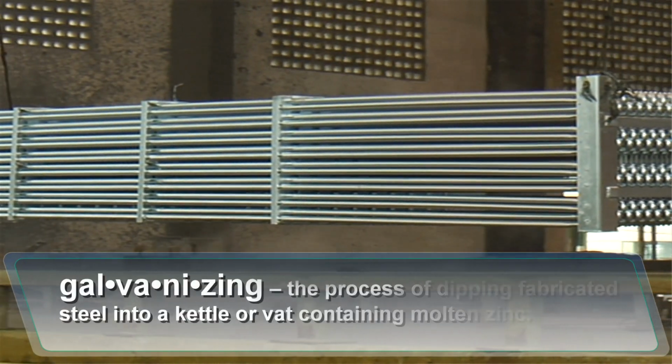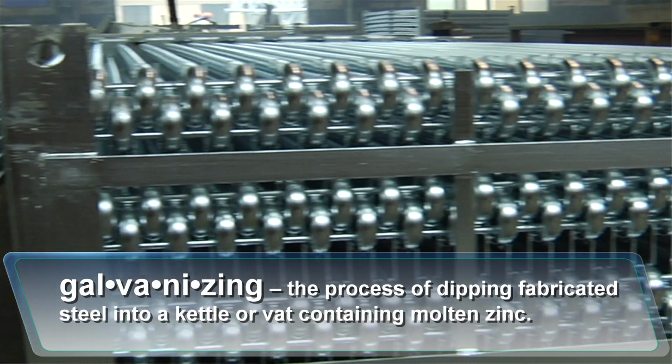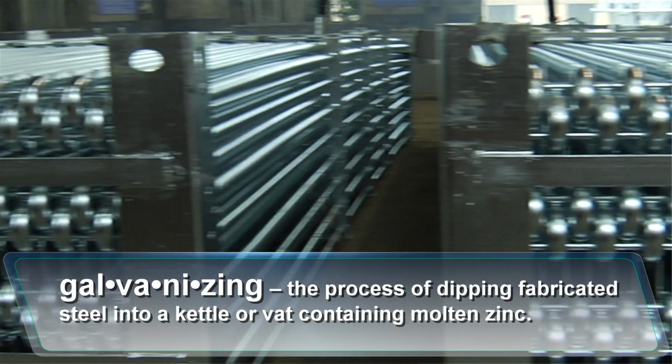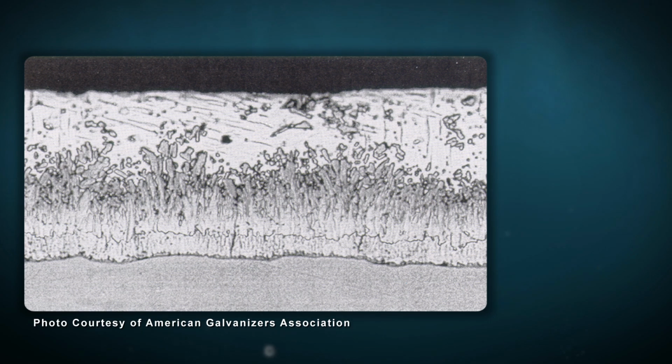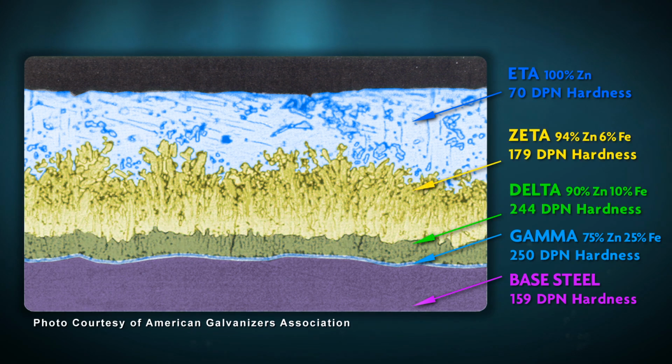steel evaporative cooling equipment. The American Galvanizers Association defines galvanizing as a metallurgical bond between the zinc and the underlying steel, creating a barrier that is part of the metal itself. During hot dip galvanizing, the liquid zinc reacts with the surface of the steel to form a series of zinc-iron alloy layers. The resultant layers of galvanizing provide the underlying steel with a coating of superior hardness, ductility, and adherence unmatched by any coating or painting process.